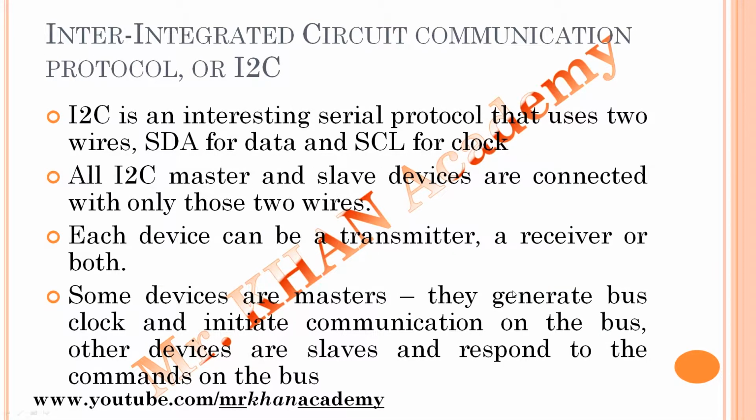Now, what is I2C? With the help of the real time clock, we get the date and time, but when we retrieve that date and time, we use the I2C protocol, the inter-integrated circuit protocol. It's an interesting serial protocol that uses 2 wires, SDA and SCL, serial data and serial clock.